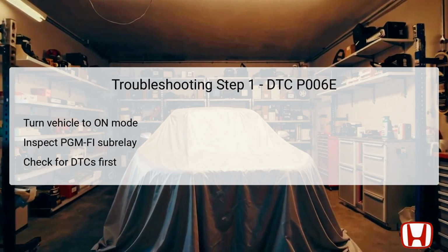The first step in troubleshooting DTC P006E is to turn the vehicle ignition to the on mode, ensuring that all electrical systems are operational for diagnostics. This stage is crucial because it allows the Powertrain Control Module, PCM, to initiate self-checks and reveal stored trouble codes.